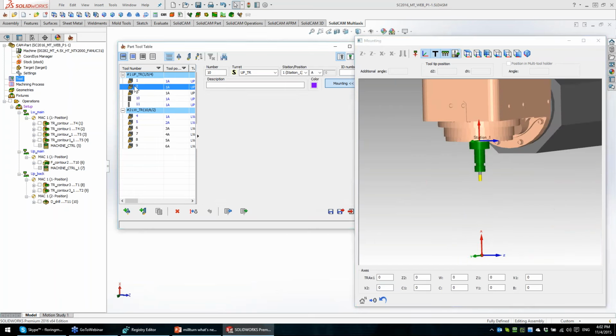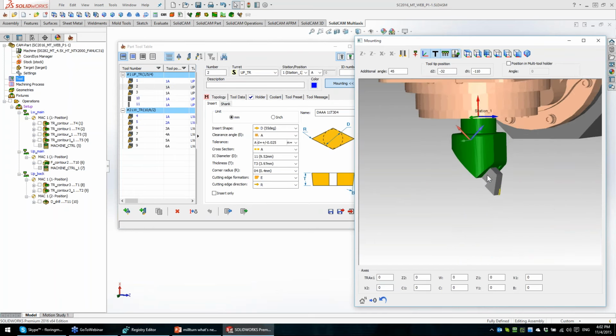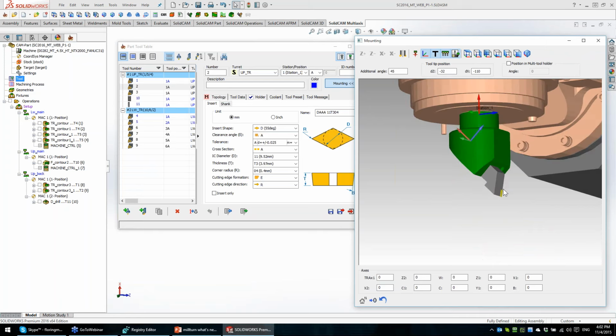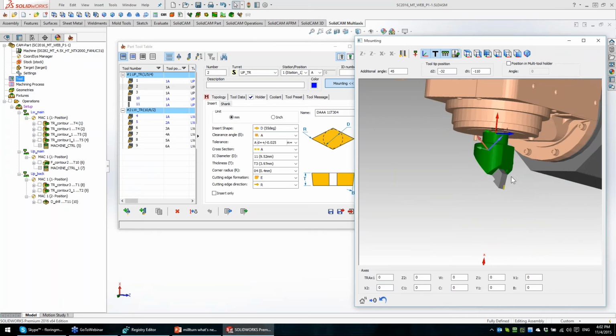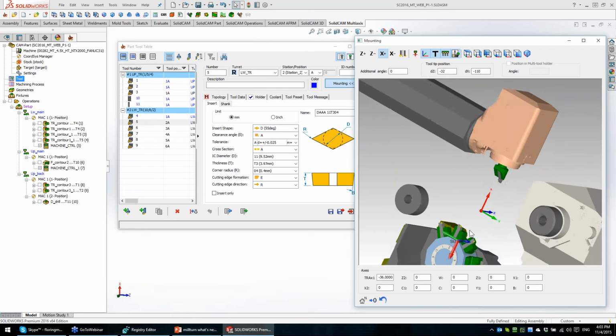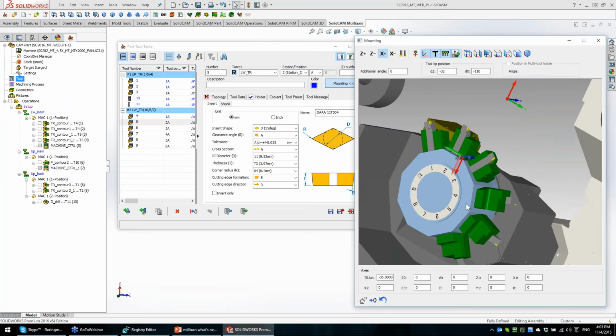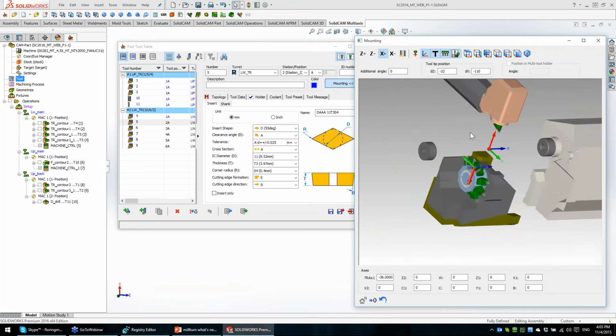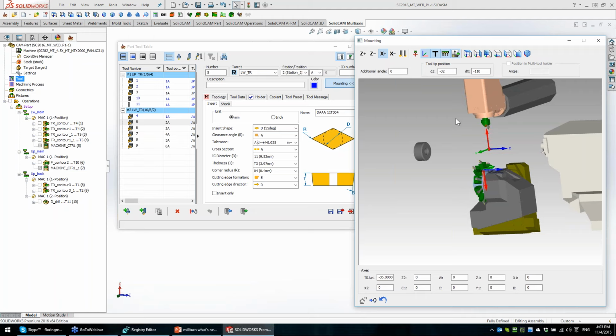Only when you select the tool is it directly mounted on the spindle and you can see and check if everything is okay. For the lower turret, you see all the tools all the time. You don't have a magazine on this rotary turret. The tools are mounted in a fixed mode. It cannot be changed with an M6. So this is the difference between a rotary turret, a linear type turret, and a spindle type turret. The spindle type has a magazine.